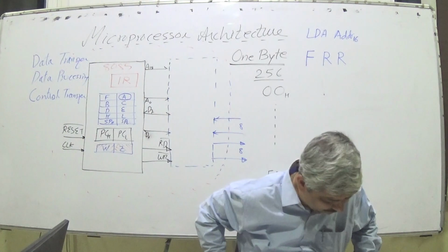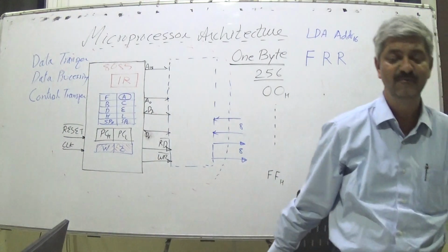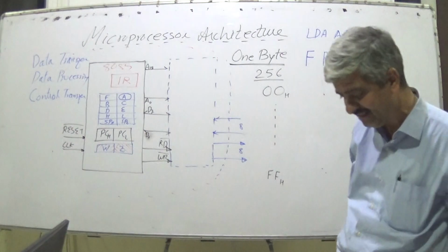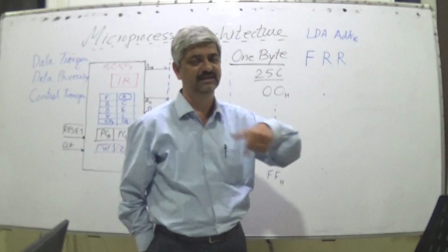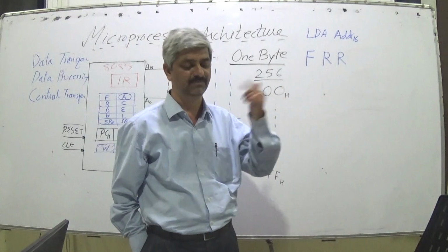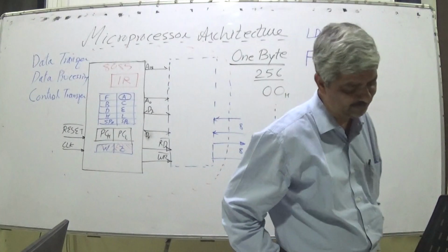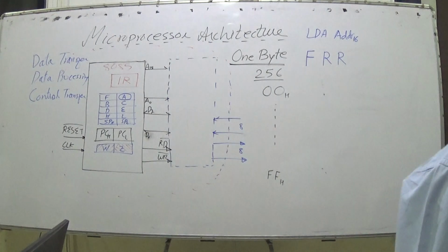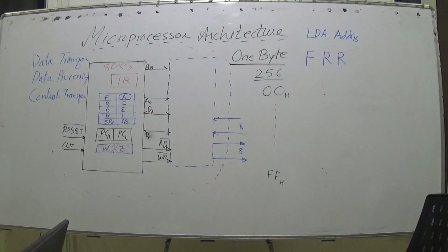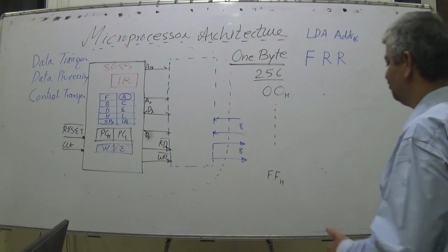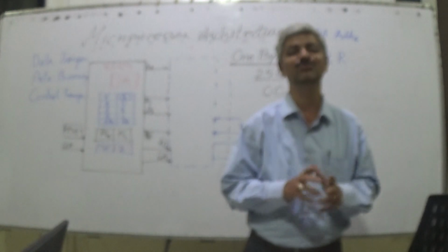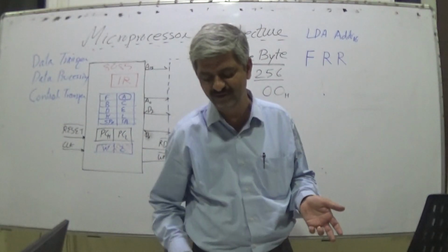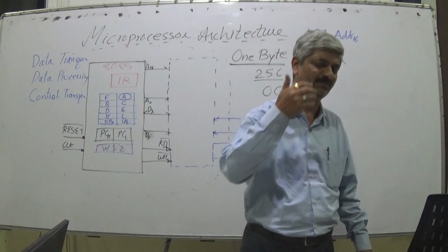So when the first byte of code is fetched, the microprocessor knows the length of the instruction, and if it is 1 byte, the instruction is completely understood and it executes that. If it is 2 byte or 3 byte, it reads further bytes. So in either 1, 2 or 3 machine cycles, the microprocessor performs a complete instruction read. The microprocessor is a servant, it is supposed to act on what is told. So various instructions are given in Google Classroom. For what purpose are they given? To be followed, but we find hardly they get followed. But that is not the practice with a microprocessor.